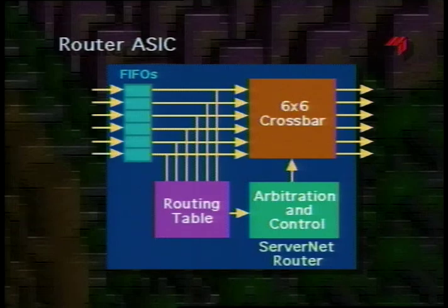Depending on where the router is actually located in the routing topology, it either looks up the high order 10 bits or another 10 bits of the destination ID that's shifted farther down in the word. This multiplexing of address bits into the routing table address greatly reduces the amount of on-chip storage required. The router also includes hardware to disable selected paths for deadlock avoidance. I'll talk more about deadlock avoidance when I talk about the preferred topologies for the network.